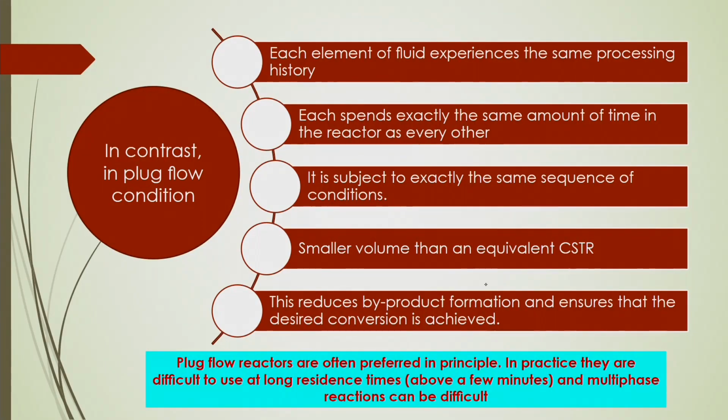Now, in contrast, in plug flow conditions we can reduce back mixing, and more residence time can also be obtained. Each element of the fluid will experience the same processing history, and each molecule will spend exactly the same amount of time in the reactor as every other, and is subject to exactly the same sequence of conditions.